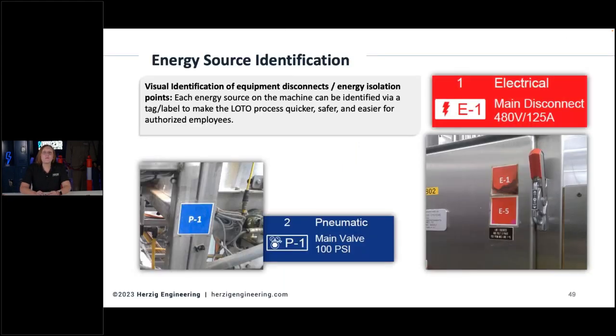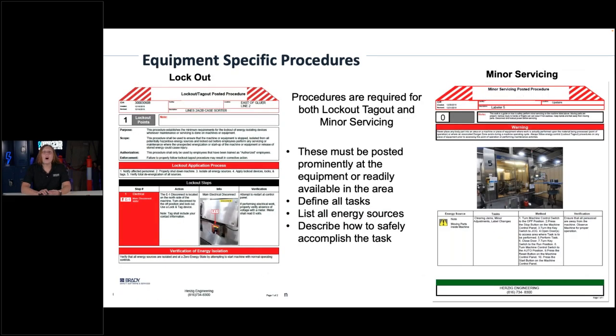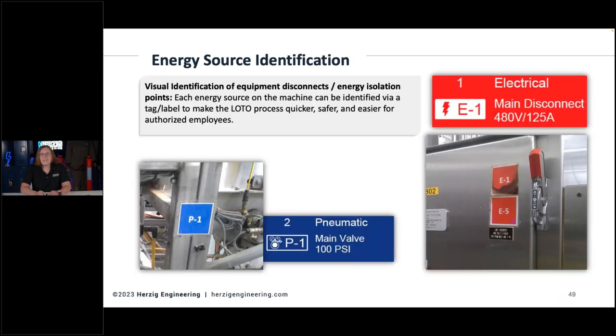Another good reference on those here, I'm going to scooch back one slide. On those specific procedures, the one on the left, for example, red is electrical. Okay, that's across the board. We identify red isolation points as electrical isolation points. Well, we could also get little tags that match up with the color and the isolation number or the device number on the procedure.